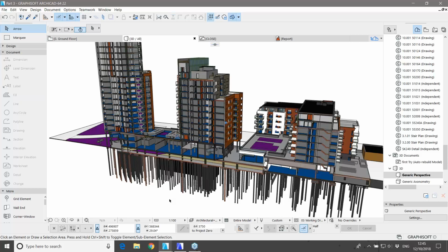You need to have a meeting before you exchange your models, to agree on the coordinates in terms of delta X, delta Y, and Z levels. And once something is decided, each discipline starts drawing their drawings in their own platforms. And through the IFCs, you just exchange the information. So that's it from me.